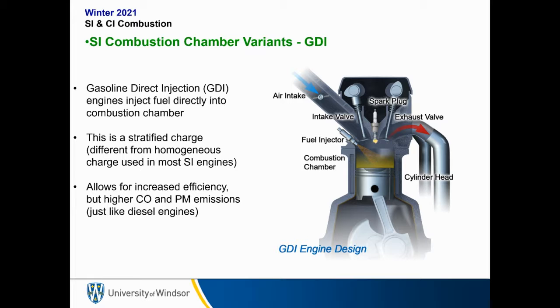pass their vehicles. Essentially what they did was they had computer logic in their vehicles where if it knew it was going through an emission test, it could detect it, and then it would implement all its emission reduction strategies, which would also reduce engine power by a good percentage. When it knew it wasn't during an emission test, i.e. during regular driving, it would disable all the emission reduction strategies and allow the engine to have more power. This just happened to be a diesel engine where this Dieselgate, or these emission testing spoofs, or how should I say, trickery, was being done.